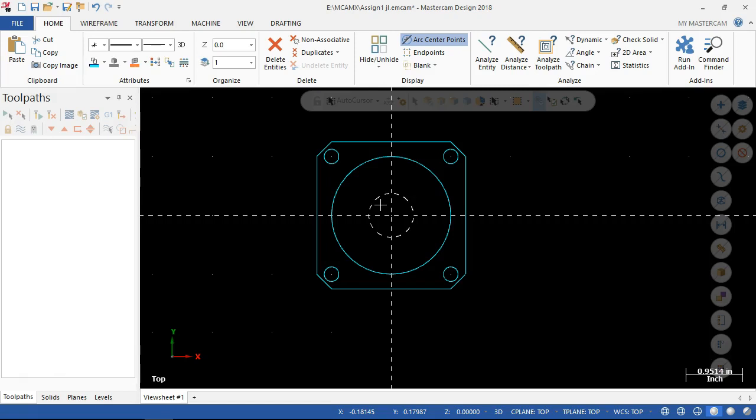All right, going into aluminum, we're going to have to discuss those tool choices. There are times where in aluminum, I'll just take the 3-flute end mill and do a circular helical bore and blow that center out, run a contour, and maybe I've sacrificed 30 or 40 seconds apart. If we're not in the mindset of we're making thousands of these, I may forego the tool change and have one extra operation with the existing tool. All right, so let's just say we're making a handful of these. So maybe somewhere between 1 and 100.